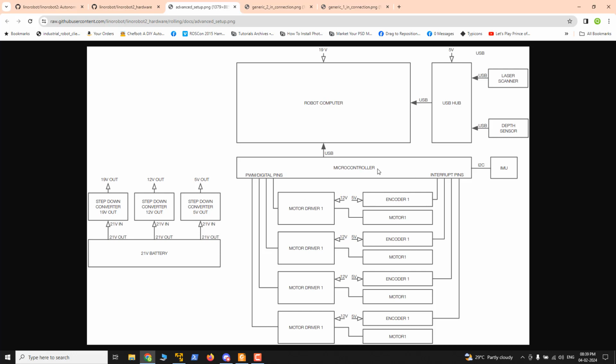And the microcontroller is running micro ROS that we discussed yesterday. So micro ROS is very similar to rosserial. Basically, we are writing the code on the microcontroller using micro ROS APIs. Micro ROS is like a micro version of ROS 2, in which you can use RCL-C APIs to program the controller. Okay, and using that you can publish, subscribe, all this stuff.